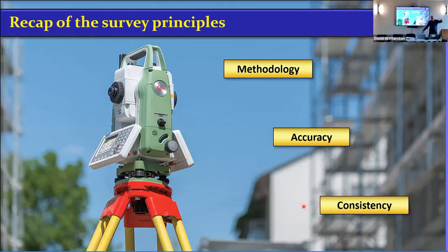So again, we had these concrete cubes in the ground with a big brass plaque on it, and you would scribe up where the centre of your control survey was. So I was putting a little light scribe on it. And this was huge. You imagine Terminal 4 was quite a big area with the car park and the whole lot. And I did it 3 or 4 times, as I said, and each scribe mark that I did was only a flipping millimetre or something away from anywhere else. And what you do is you process it, then you correct it, and then you go back to site and get it exactly on. It transpired that the guy was checking the work.